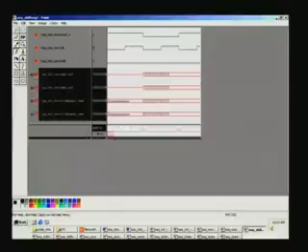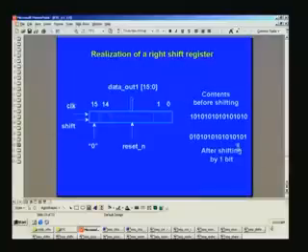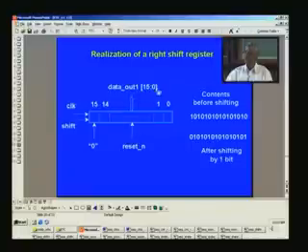So in this shift register we had a 16-bit shift register and a data out can be had here, and we had two types of shift register, data out 1, data out 2, both primarily same, except that the way of writing the assign statement for shift was different.